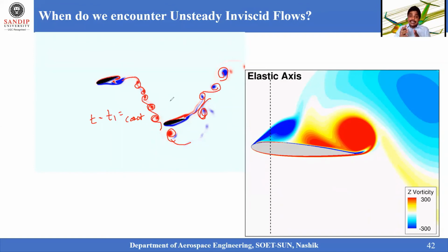Then later we'll introduce time into that steady flow, and we will say that at this instant t, this is steady flow. At this instant t plus 1, this is again steady flow. At this instant t plus 1, it is again unsteady flow. So as far as the computational approach is concerned, we will split it at the different times t1, t2, t3, t4, t5, t6, t7. Then we will club all the solutions of the steady flow and vary them with respect to the time. Then you will get the resultant variations like this.